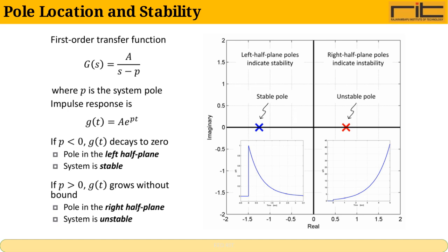safety and reliability of our infrastructure. Properly positioning poles helps us maintain structural integrity while accommodating environmental factors like soil conditions and terrain. Stability is essential to prevent poles from leaning or falling, especially during adverse weather. By carefully selecting pole sites and considering factors such as soil strength and load requirements, we enhance the overall durability and safety of the installation. Understanding these concepts helps us design and implement more resilient support systems.